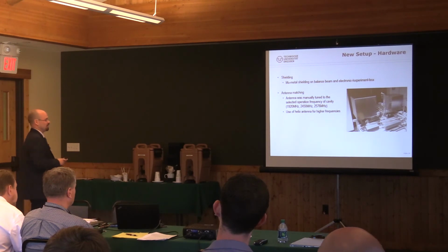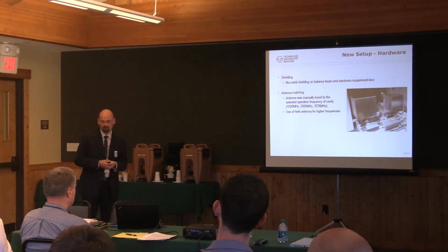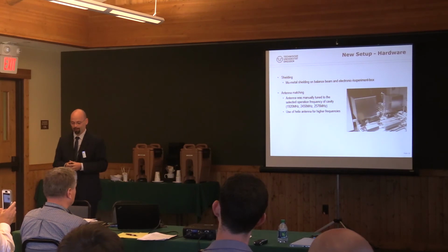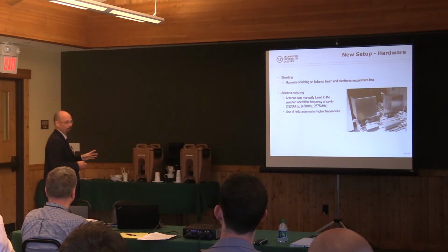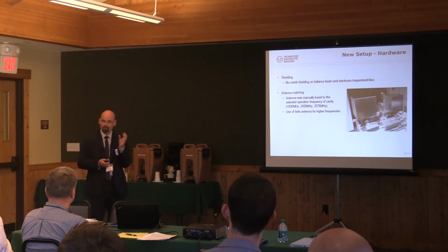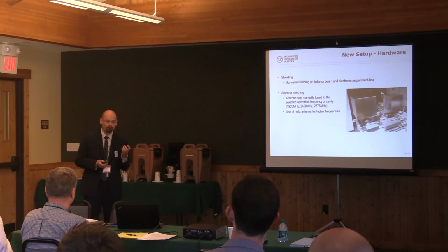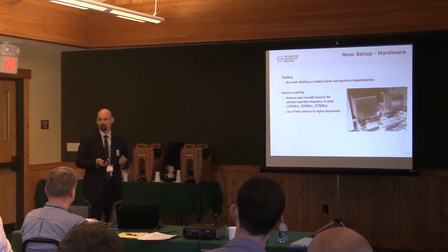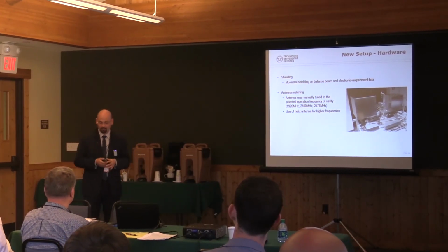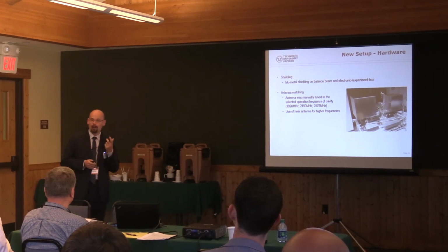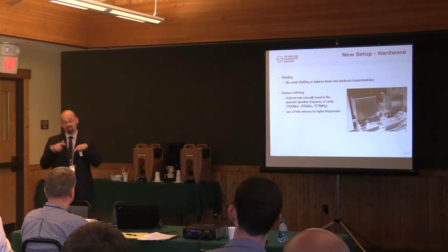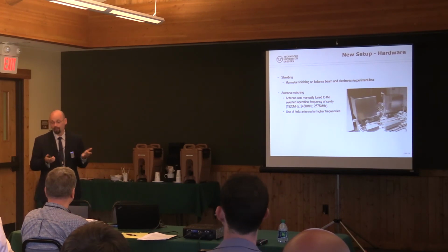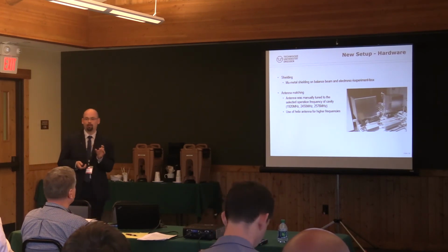The reason is easy: I wasn't able to build a loop antenna for a higher frequency than 2 GHz. All my attempts to build a loop antenna for higher than 2 GHz resulted in loop antennas getting smaller, smaller, and smaller, and we also showed 1.9, 1.8, 1.7. Today I think it's a problem of my N-type coupler, which is the basis of my loop antenna. The geometry of the N-type coupler and its capacitive behavior doesn't allow me to reach higher frequencies.